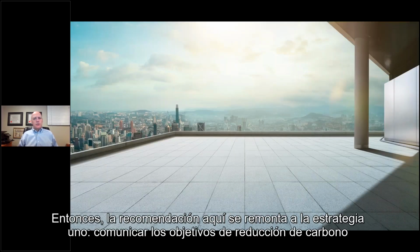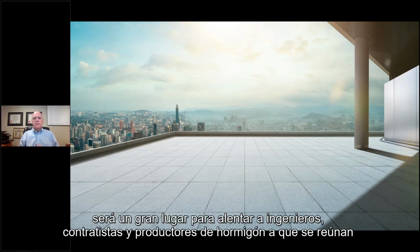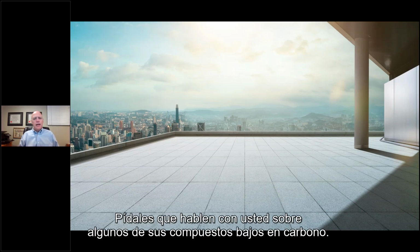The recommendation here goes back to strategy 1, communicating the carbon reduction goals to contractors and producers during the design process, which is critical. Let them know that you are looking for innovative solutions. Design charrettes would be a great place to encourage engineers, contractors, and concrete producers to get together to demonstrate or show what opportunities there are in bringing innovation to the project. Most sophisticated producers are experimenting on new formulations all the time. Ask them to discuss some of their low carbon concretes with you.